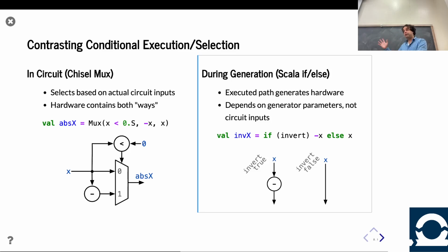Now, the other languages are high level synthesis, HLS. There you say, I want something that does this computation, and you give the tools a lot more freedom to say how they want to do it. The tools can choose how much to pipeline, how much parallelism, and that kind of stuff. And so Scala, at the end of the day, is still a very literal language, right? When you say I want this hardware component, you will get that hardware component. The productivity benefit comes from the fact that when you want to change the structure of those hardware components, you can do that in a programmatic way with parameters. I don't know if that quite got to your question, okay, great, thank you.